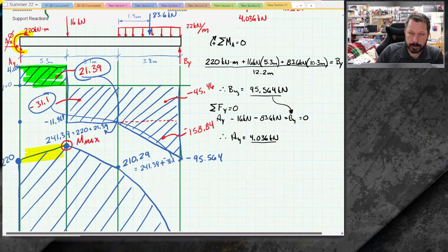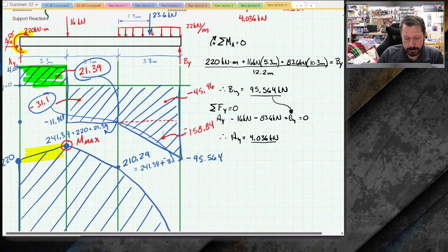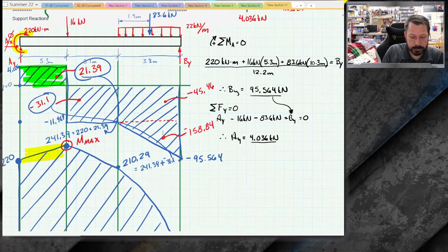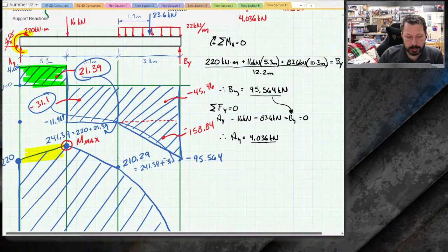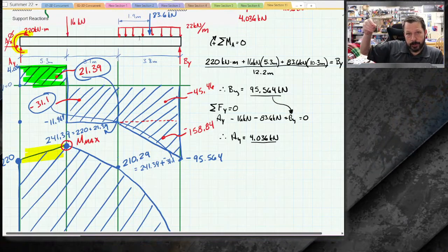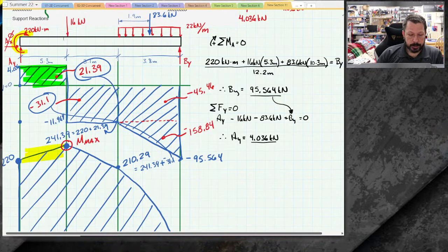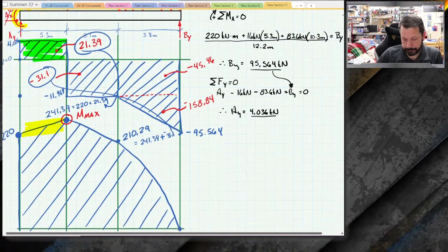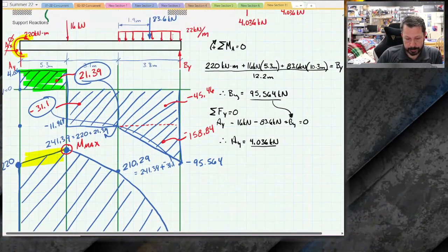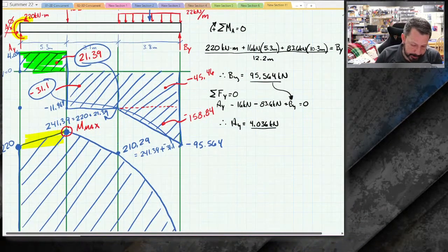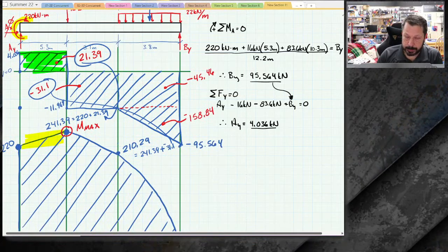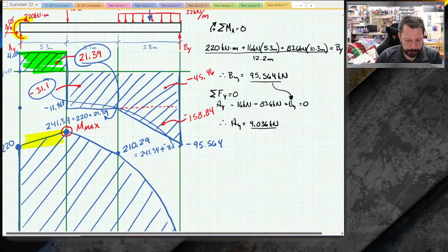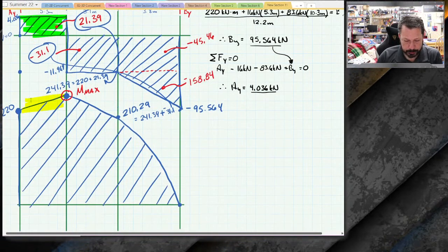So your shear diagram is going to look like rectangles. Sometimes there'll be triangles. I guess there could be other shapes, but in this course we're only going to deal with stuff that creates rectangles and triangles. The triangles are going to be under distributed loads because the distributed load is gradually increasing the shear, whereas point loads instantly have a step change in the shear, and so that just makes it look like rectangles everywhere. So hopefully that helps. The easy explanation is that you just add on the area for that interval of shear, and that's how you get from point to point in your moment diagram.